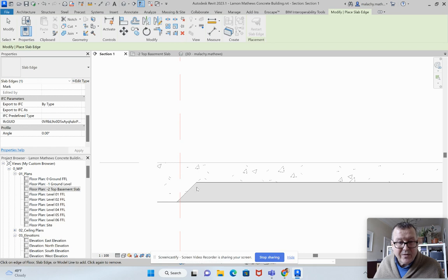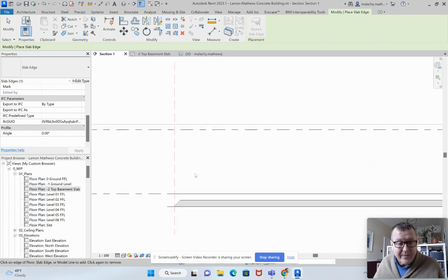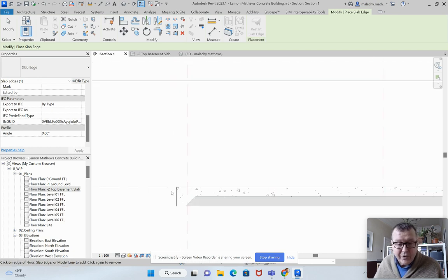You want the thickening to be fully in a position to support that point load. So that thickening is not the right size in this case here. Now, so two choices. I can move the floor in, which will consequently move the thickening in a little bit, but I want that little edge there for the moment.